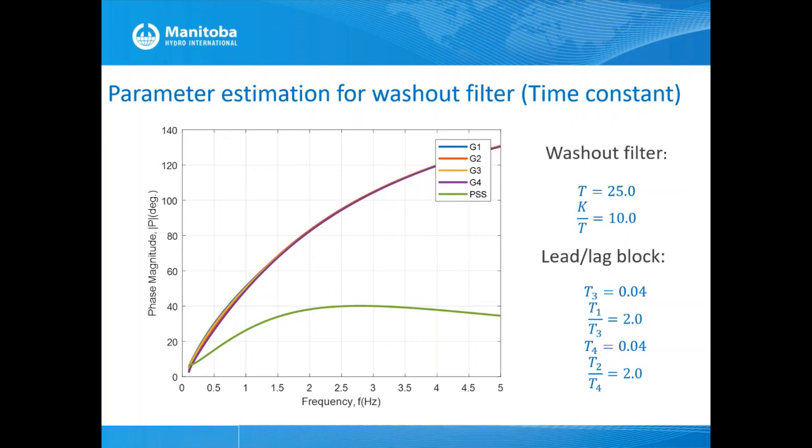So we use eigenvalue tools, which are essentially linearized tools. That's why we have to look at a number of operating scenarios. My rule of thumb is when you tune a PSS, you then check the performance in time domain simulations to check the behavior. It can be RMS simulations like PSS/E, and you might also want to check similar situations with EMT tools like PSCAD to see whether there are any negative torsional impacts.